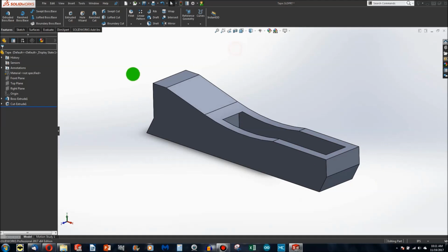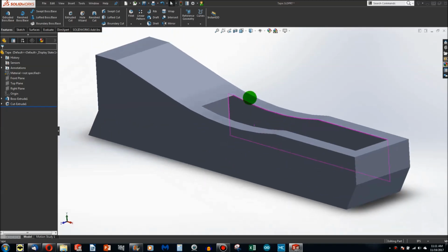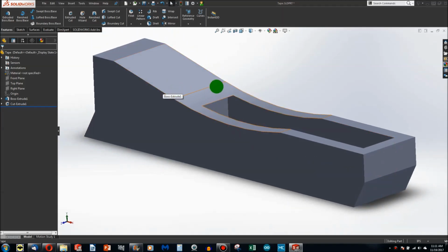And that's why it's so important to orient the views like we talked about in some of the first videos, according to the front, top, and right planes, so that the part will orient correctly the way you intend. This menu enables me to change the appearance of the part so I can get rid of some of the hard lines, and notice no tangent line here anymore. Tangent line here, and it's gone. So this view can make for a little bit more of a realistic rendering. It's called hard lines removed.